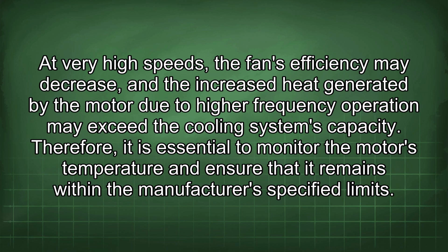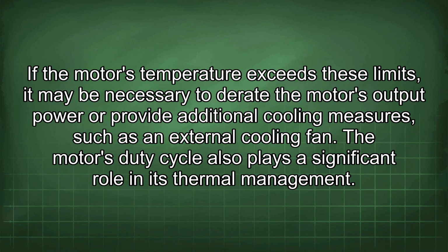Therefore, it is essential to monitor the motor's temperature and ensure that it remains within the manufacturer's specified limits. If the motor's temperature exceeds these limits, it may be necessary to lower the motor's output power or provide additional cooling measures, such as an external cooling fan.